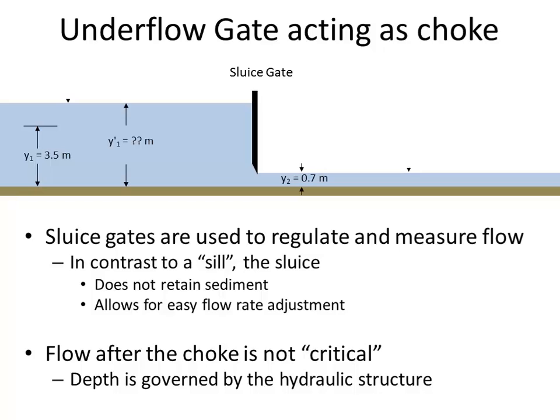And so when we put the velocity head term in with it, that means the original specific energy available is much lower than what's required for the flow to get under that gate. To get under the gate, the water's going to have to be moving very fast. It has a huge velocity head.